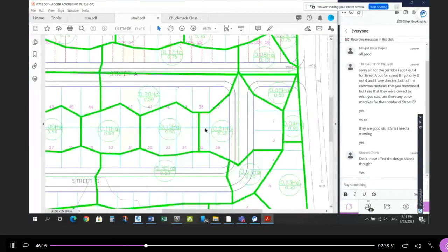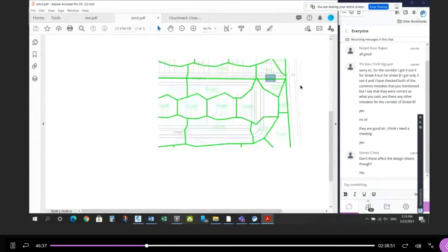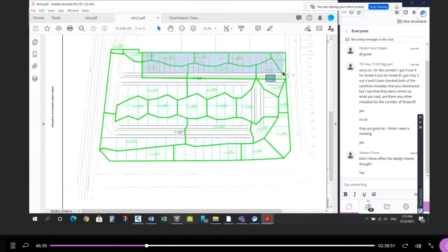So if you add a little extra to here instead of here, right? If this is in the wrong spot a little bit, eventually both of these areas are going to be added together to get the pipe down at the end, right? So eventually it kind of takes care of itself. So it's more sensitive than sanitary, but it's not that sensitive. Okay, so there's a lot of leeway here as well. Again, there's different runoff coefficients for the townhouse area versus everything else, which is single detached, right?